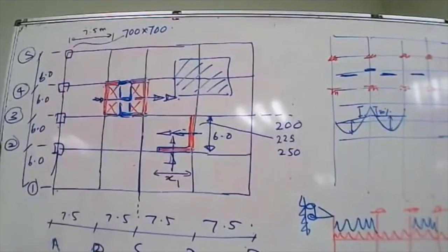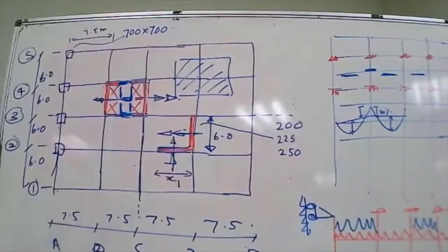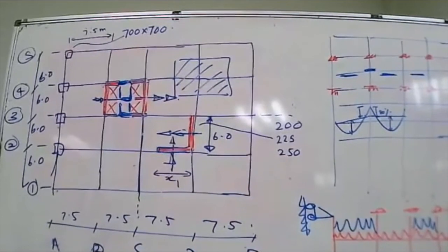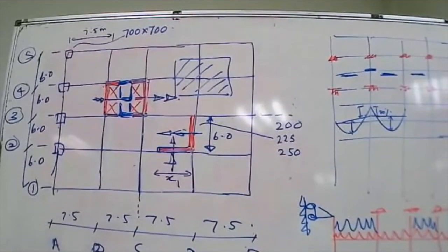One rule I generally use is I will make sure that all the bottom reinforcement continues up to within 0.3 meters of the support. Within 0.3 meters of the support, then all these minute problems will be looked after. Did you get the point?